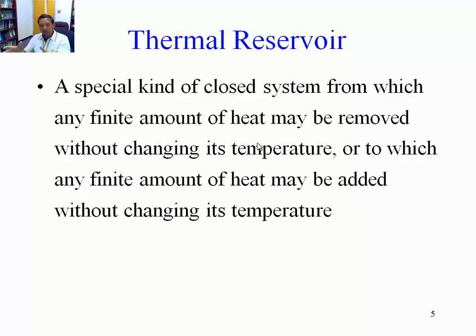It is at 70 degrees in the case that we're analyzing right now, and we assume it is going to be at 70 degrees, even if we dump an enormous amount of energy into it, or if we subtract an enormous amount of energy from it. Okay, so that's the notion or definition of a thermal reservoir.